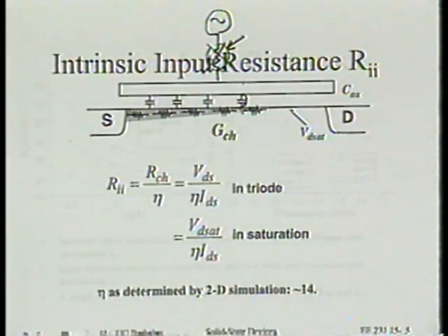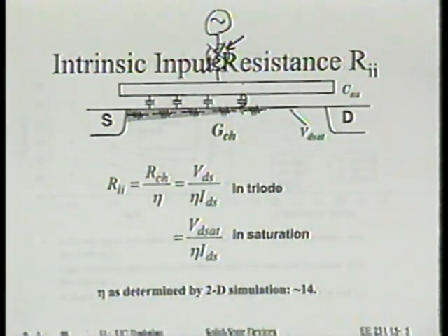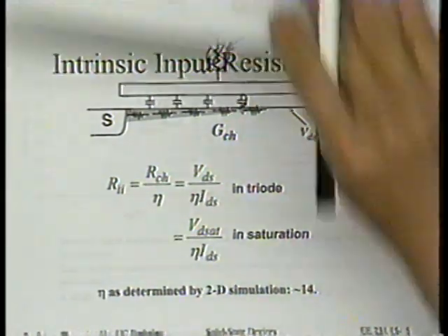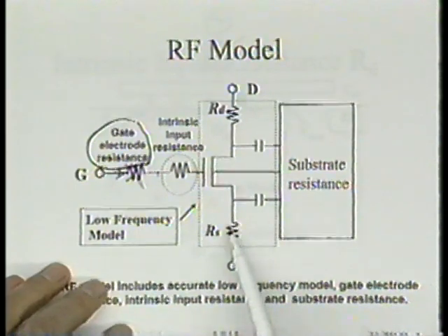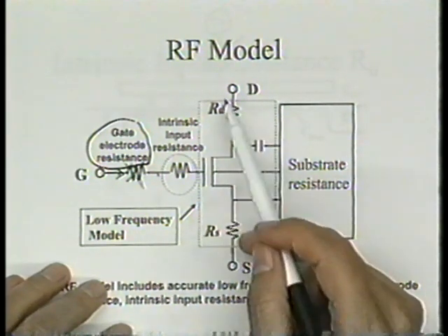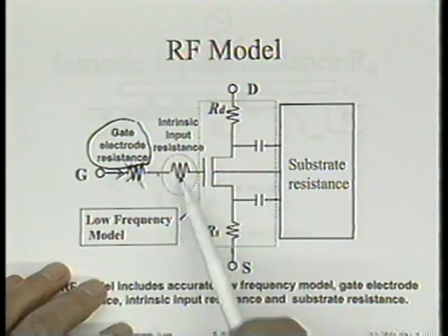You follow what I'm saying? In other words, this resistor has the same effect as the polysilicon resistor, right? But in terms of a compact model, of course, it's much easier to put that resistor on the gate side, not put it into the source or drain side, because otherwise you're going to mess up the DC characteristics. Is that right? So you're going to put this on the gate side.